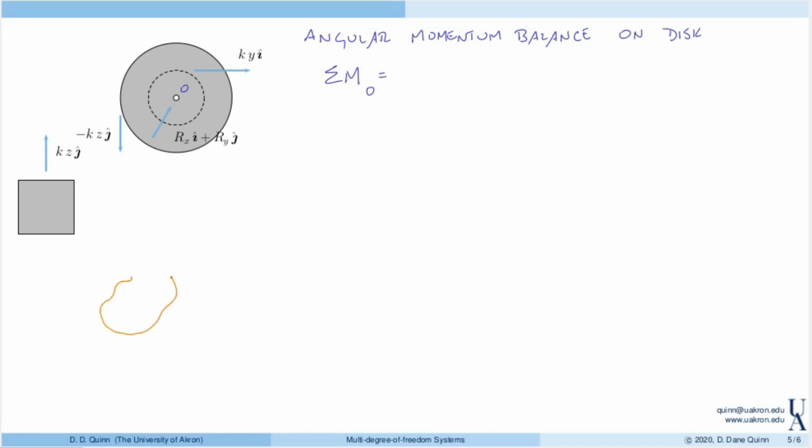Right, so imagine you have an object here, and you have a force here, F, that's acting at, say, a point P, and I have a second point, A, here, and I'd like to find the moment about A. It's the position of P with respect to A. Right, so we call that R_P/A, cross the force itself.